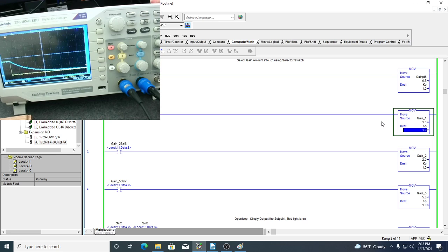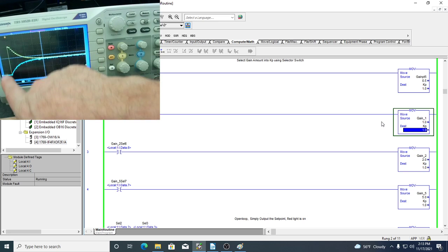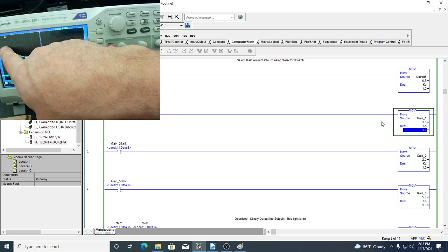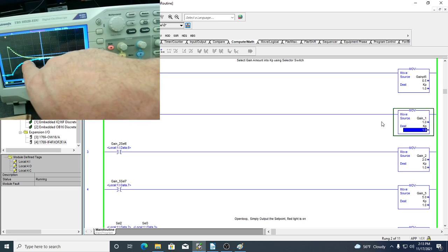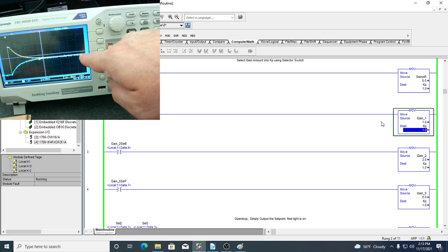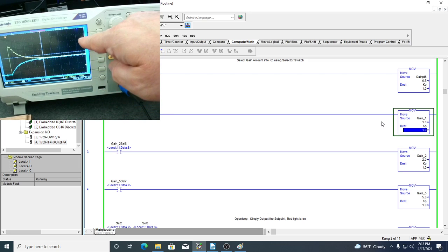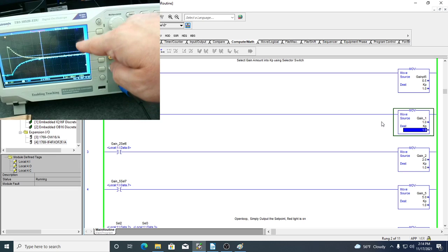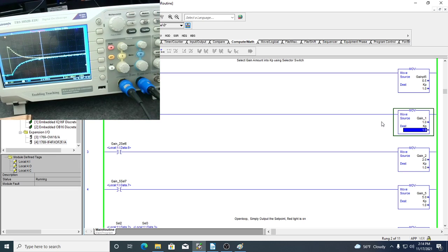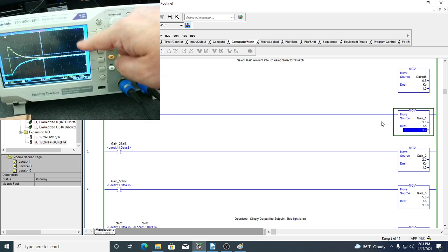And now I'm going to energize this. So this is with a gain of 1. So I doubled my gain. So you notice how now it jumps way up here to 5, but then it drops down. So the system responded faster, and it has less steady state error, because remember, it's supposed to be all the way up here at 5, and it's not. Okay, it's still at maybe 2.5 or so. So there's still quite a bit of steady state error in here, but less error than we had before.